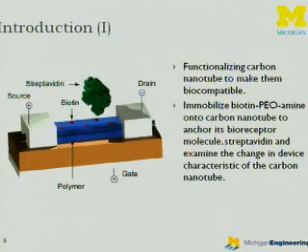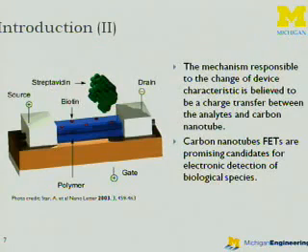For your information, biotin and streptavidin naturally bind or couple together, and then we examine the change in device characteristics of the carbon nanotube. The mechanism responsible for the change of device characteristics is believed to be the charge transfer between the analytes and the carbon nanotube. Hence, from the changes in device characteristics, we can infer that there is some kind of specific protein binding to the carbon nanotube.